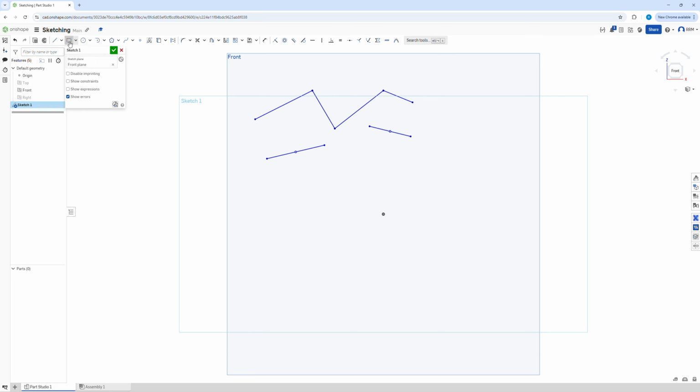I've also got a corner rectangle up here, so I can click once, drag out, click again, and have a rectangle. Or I might want to go for a midpoint rectangle. So I click once, let go of the mouse button, drag my mouse out, click again, and you can see that this rectangle is again from the midpoint symmetric. Well, not symmetric, but it has basically spread out from that middle section.